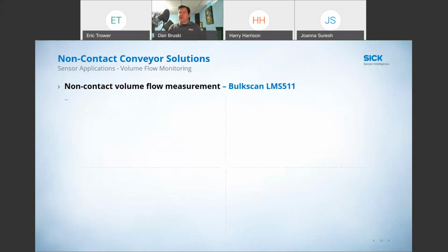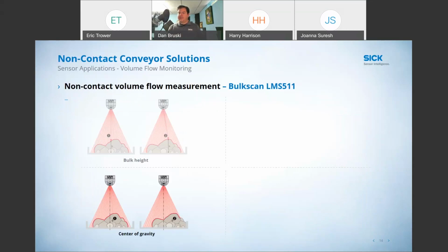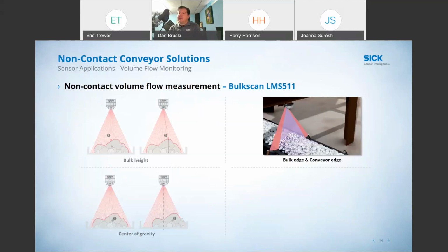Using infrared laser technology gives us a possibility to determine the volume or mass flow on the conveyor belt, like we've been talking about, but the laser beams also tell you the exact height of material on the conveyor. By doing so, large rocks and other things, especially if you're running alternative fuels, can be detected in a timely manner, and downstream equipment can be protected by stopping the belt before any damage occurs. Also, the probability of overfilling is minimized by using this height information.